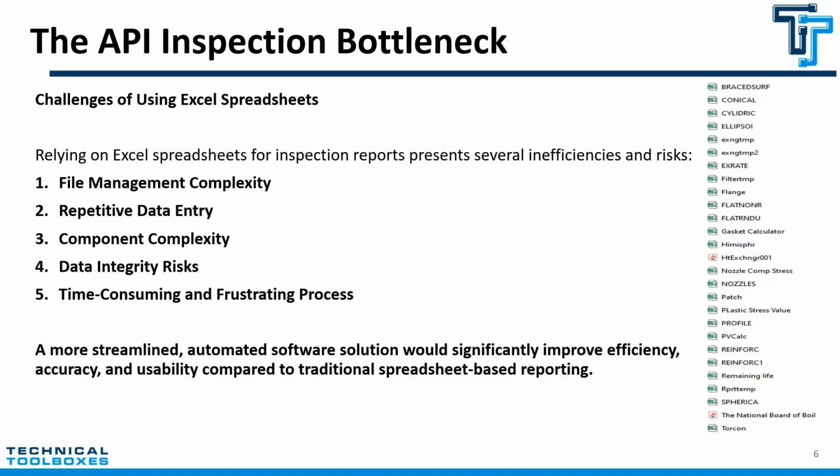This process requires careful searching and organization, leading to wasted time and potential errors. Some of the more complicated calcs, such as horizontal tank evaluations in accordance with the Zick formula, Appendix M calcs for tanks greater than 200 feet, are often not a part of the Excel component library. So you may not have all the spreadsheets that you need to do a really comprehensive evaluation.